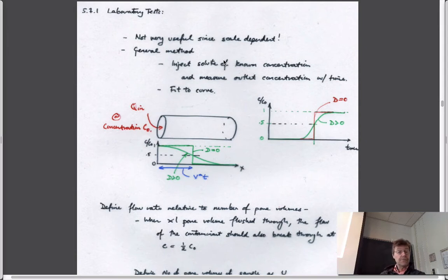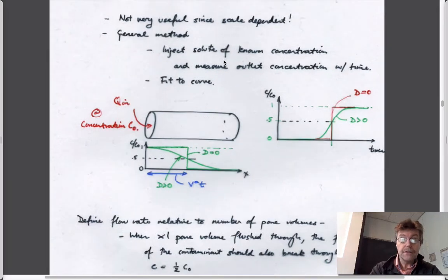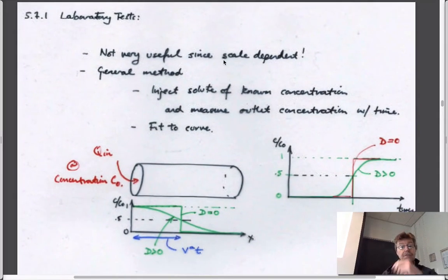You'd think that that would be useful because you could take samples out of the field, you take them back to the lab, and then you do experiments on those samples. And the experiments that you do, you could imagine, would be just the same as what we've talked about in terms of our calculations of transport downstream, is that you would turn on a concentration magnitude at an upstream face at time t0, so that the boundary condition at that upstream face would look like this with time. This would be C over C0. And you'd hold it on for all time.